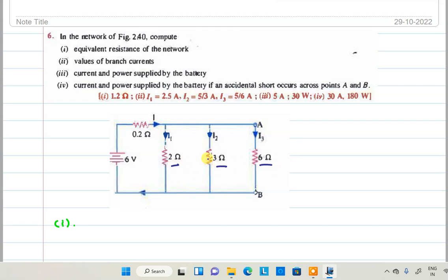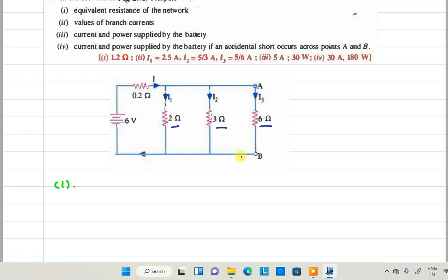So first find out, always you find the resistance from the opposite side to the supply. So you should follow the resistance from this side. Don't consider these two as parallel and parallel. If you are doing that, that is wrong. So everyone listen, this is a 6 volt, right? You should find out the solution from the opposite side, then only we'll get the correct answers. Then we are finding out these three are connected in parallel.